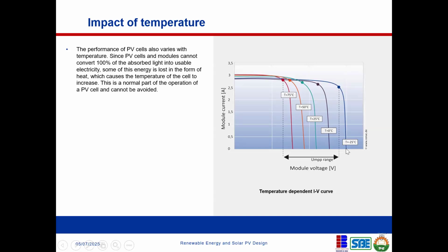The voltage is good. It's high. It has a very high voltage, right? And then look at the current. The current is also high, right? I mean, at this temperature, let's assume that the sun is already fully out, but the temperature has not increased, right? So in that case, the current is high, but once the temperature of the module begins to increase,